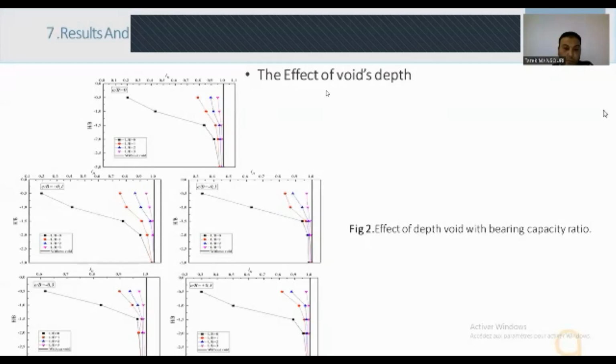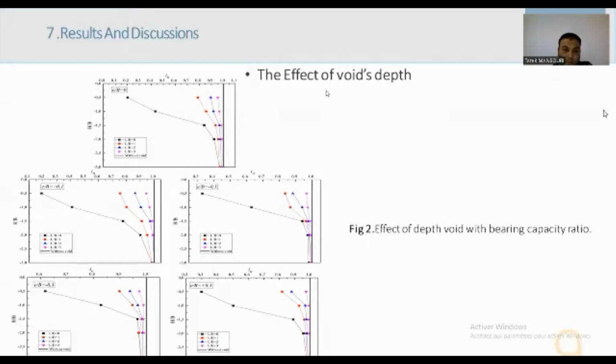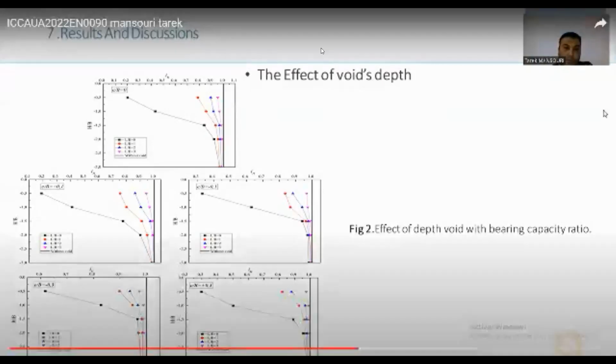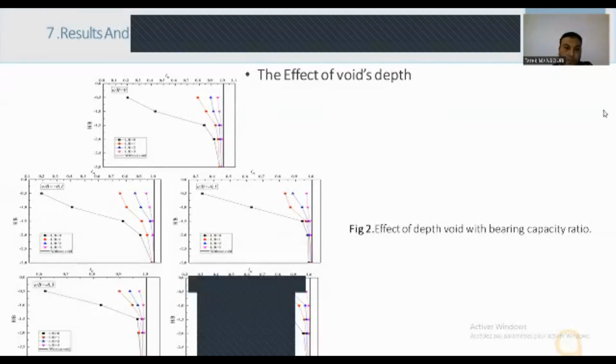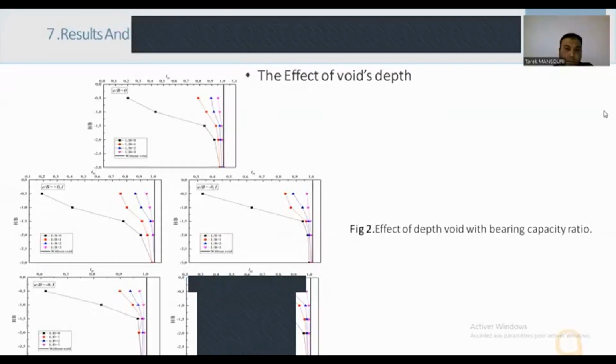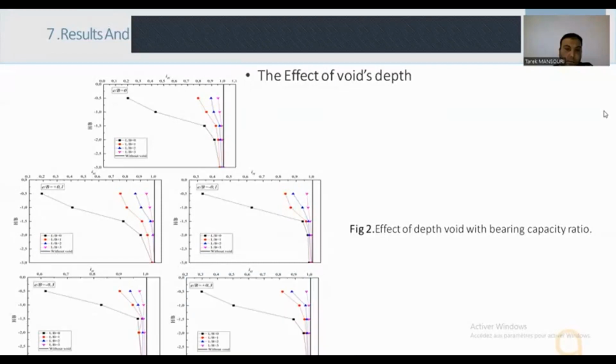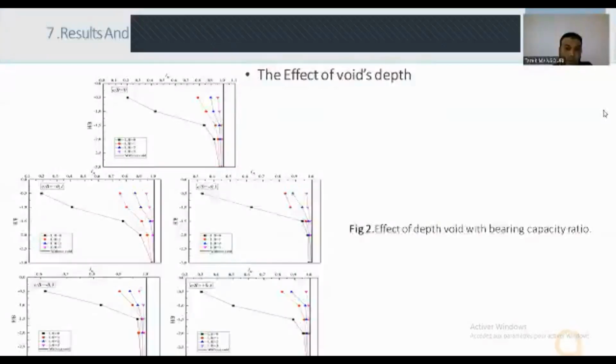Then, an increase in the negative load eccentricity direction of the slope reduced the void embedding effect, as we suspected. Moreover, the h on b effect was less influential for negative eccentricity than for positive eccentricity. This can be explained in that for negative eccentricity, the loading point moves away from the center of the void and thus leads to an increase in bearing capacity.